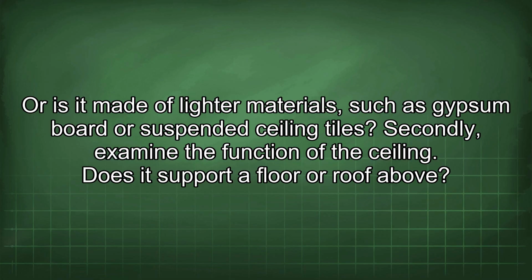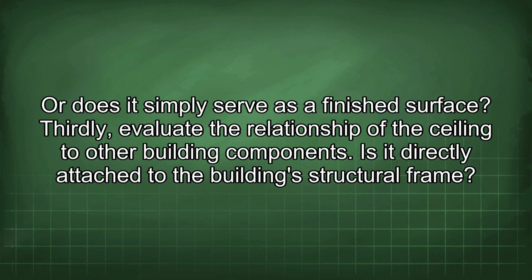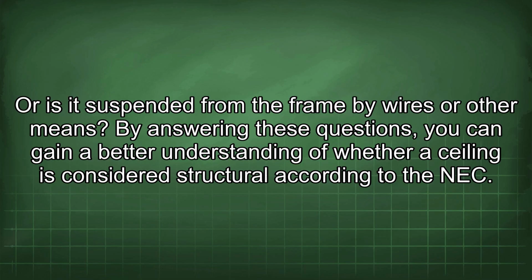Secondly, examine the function of the ceiling. Does it support a floor or roof above? Or does it simply serve as a finished surface? Thirdly, evaluate the relationship of the ceiling to other building components. Is it directly attached to the building's structural frame? Or is it suspended from the frame by wires or other means?